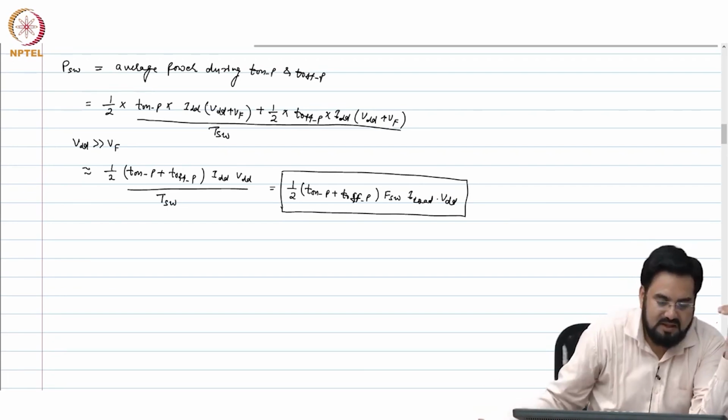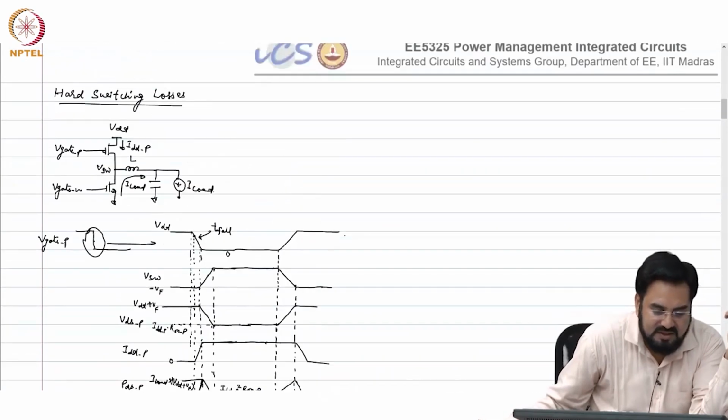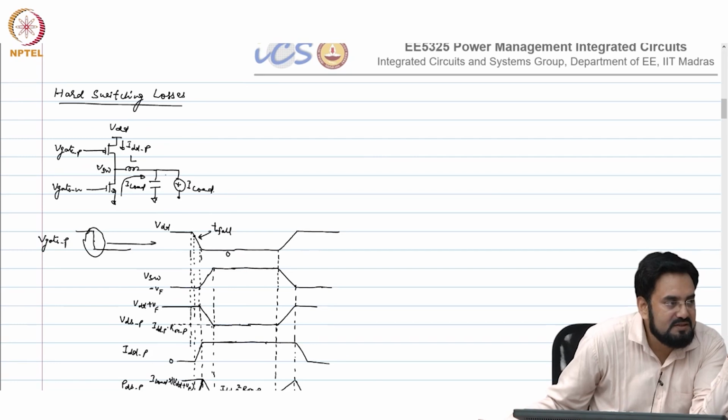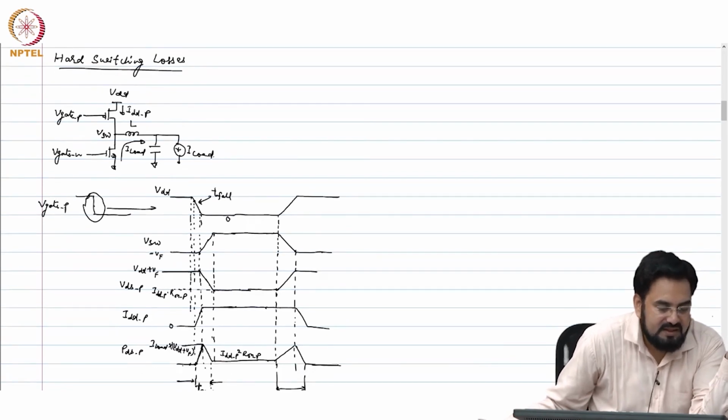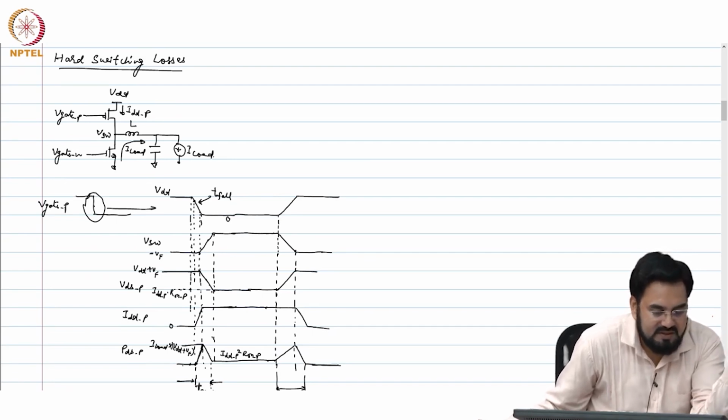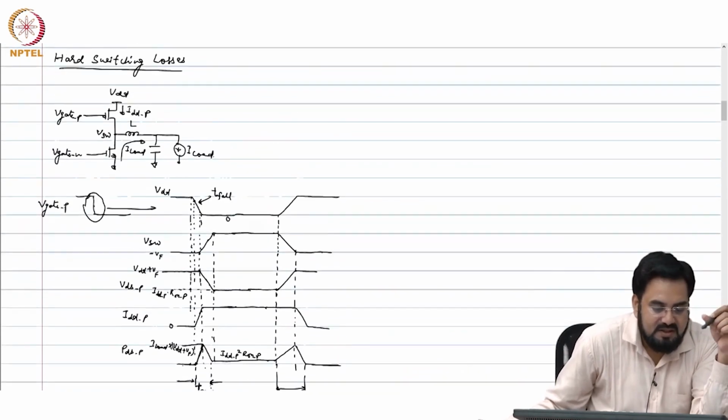So, you have to look at how fast gate is charging. So, that will obviously depend on your gate driver and the capacitance on this gate, and there are some intrinsic delays of the transistor which are specified in the data sheet. But if you are using on chip MOSFETs, you have to look at the simulation.